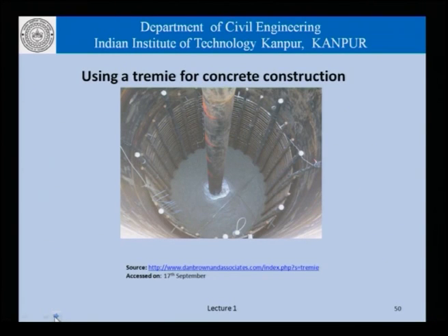This slide shows construction of concrete with a tremie. Now, in this case, concrete is being deposited at depth, possibly underwater, using a tremie. Now, the concrete is being dropped all the length of this pipe, and it needs to be ensured that the pipe is always embedded in this concrete. As more and more concrete is dumped in, the concrete rises in this formwork here, and the construction process is completed.